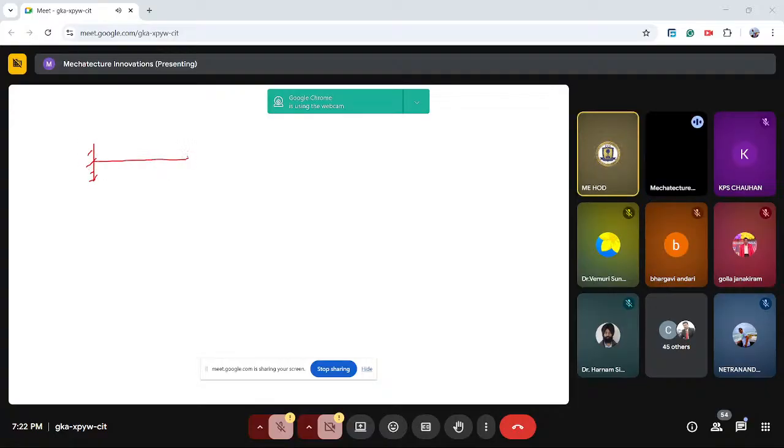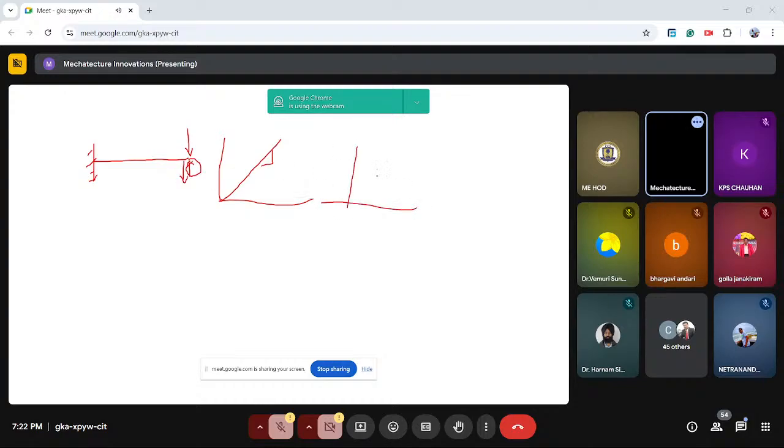You see, this is the cantilever, and I am applying a force downwards. So the reaction force from the cantilever will be against my force. This is called positive stiffness. When I draw the force-displacement curve, assume it is a line. It will have a positive stiffness. But when the reaction is also towards the force, then I will have negative stiffness.